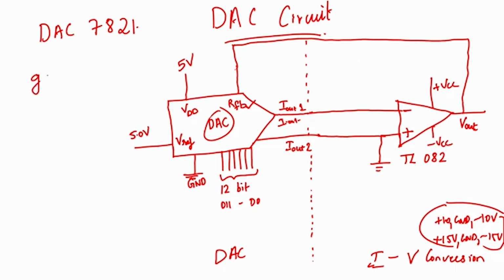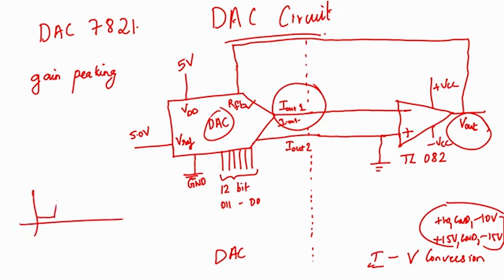What happens is, occasionally for a fluctuation in input voltages or output current, we might get saturation output voltage as blips in the output. Let us say the output is supposed to be like this, and sometimes because of blips we will get it like this, and this will be Vsat, the saturation voltage.